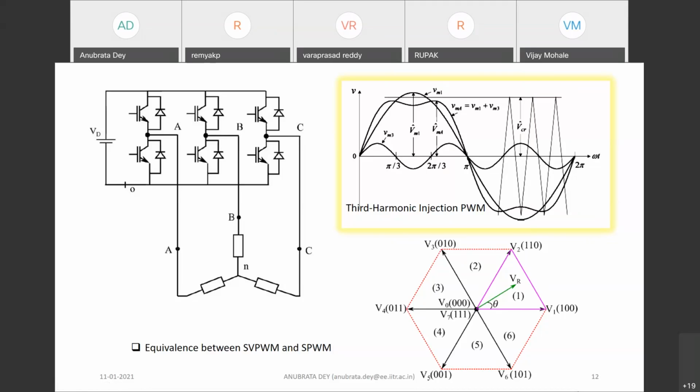The basic fundamental idea of using PWM operation of any inverter is that you use sufficiently high frequency carrier waveforms to compare, and these carrier waveforms will determine your switching frequency of the inverter. That determines the output nature, what the dominant harmonics will be, determined by these switching carrier frequencies.